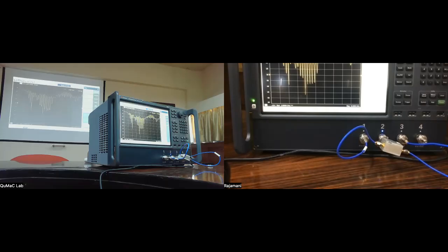And again, many of these rely on some kind of interference phenomena. And that again happens ideally at some frequency. So there'll be an ideal frequency of operation, and the operation will get progressively worse as you go away from that ideal frequency, like we saw for impedance matching circuit or impedance transformer circuit, right? The transformer is defined at one frequency, and then it gets worse as we go along. So similarly, these things also have that. So it just happens that this particular splitter has a response like this. We will compare this with another type of splitter just immediately after this.